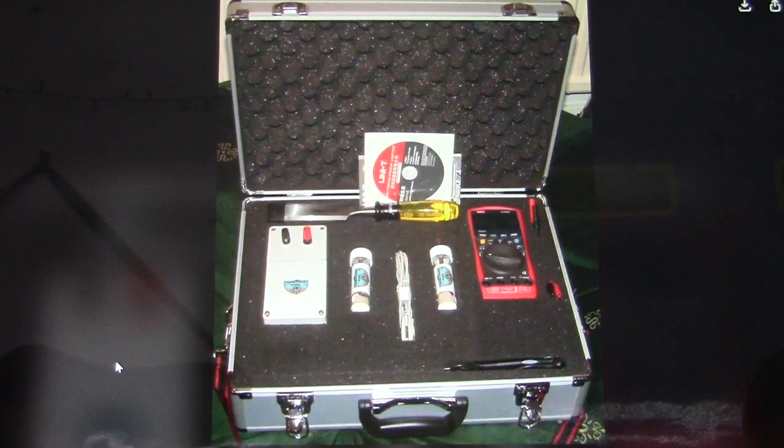How the Alexander cell works. The Alexander cell operates by creating a controlled corrosion environment. It includes an earth path that allows the device to be influenced by current from a cathodic protection system. When in use, this influence can be observed through a current meter, an ammeter, showing whether corrosion is occurring or being prevented.